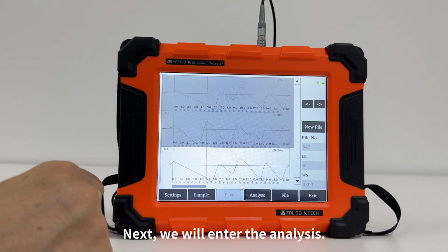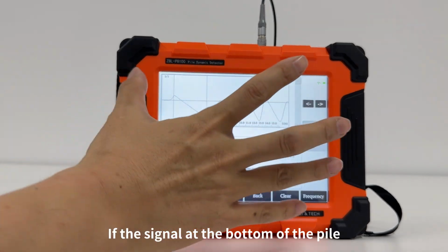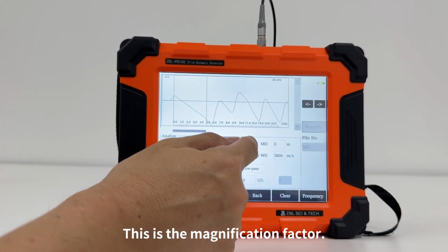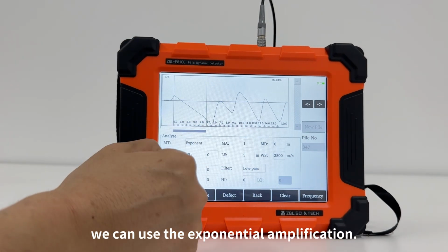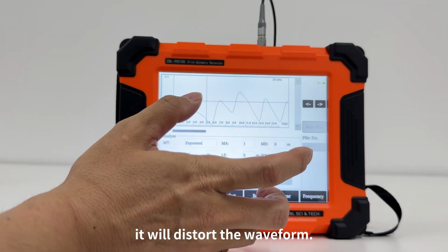Next, we will enter the analysis. This is the exponential magnification, which we use more often. If the signal at the bottom of the pile is not particularly obvious, you can scale it up exponentially. This is the magnification factor, to amplify a certain multiple. Generally speaking, if the signal at the pile bottom is not obvious, we can use the exponential amplification. If you adjust the magnification too much, it will distort the waveform.